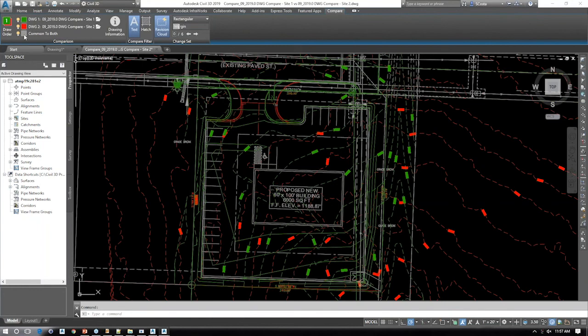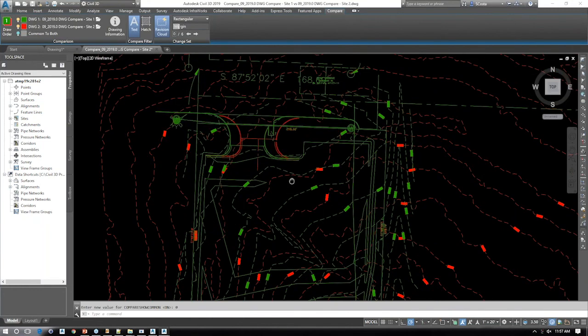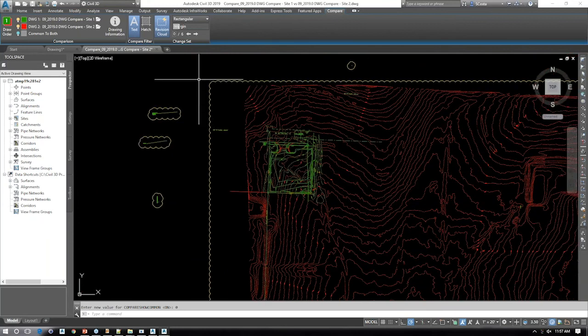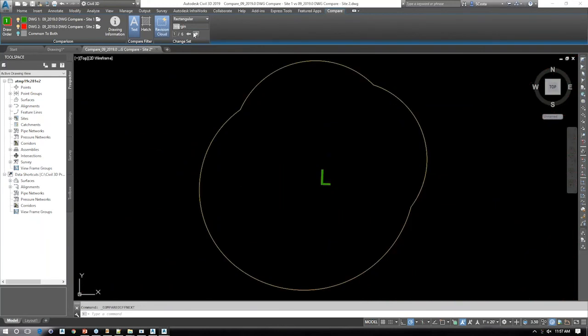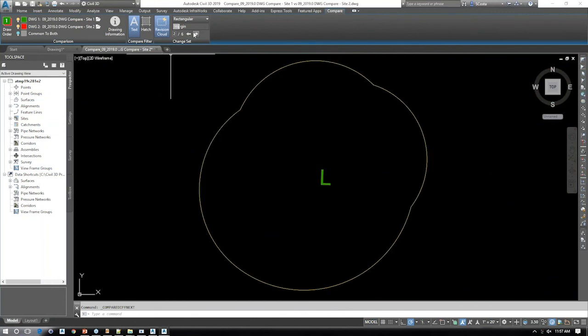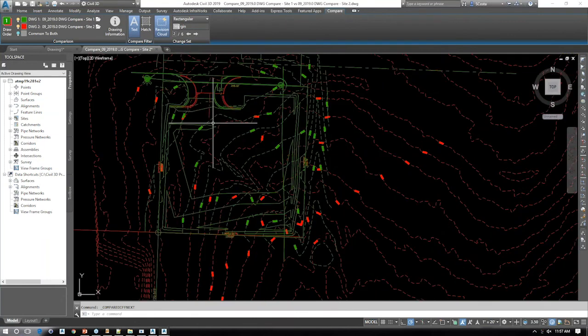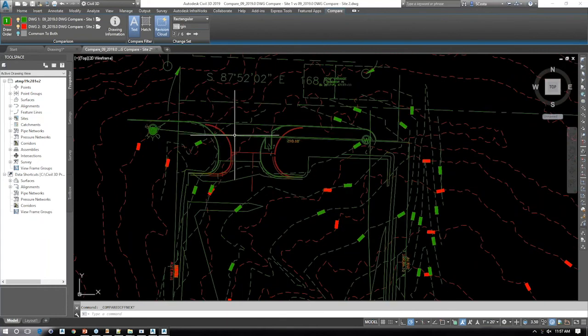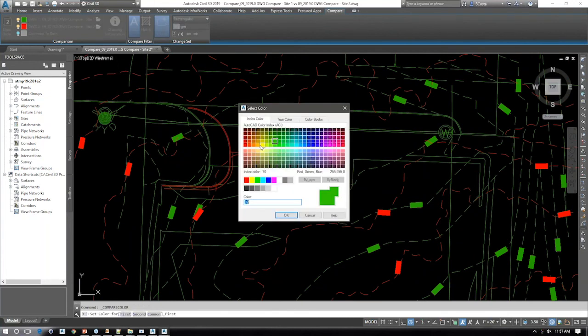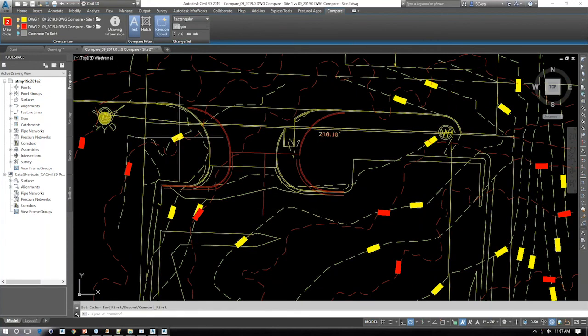So you can see here that I can disable what's common to both, and I can analyze via color coding, green and red, the differences between the drawings, right? You can see that it's gone through and added a revision cloud that I can step through all the individual changes that are in that drawing. And so it gives you a very quick and easy way to understand which elements are which. You can choose the draw order from what's drawn on top. You can choose the different colors depending on what's easier to visualize for you.